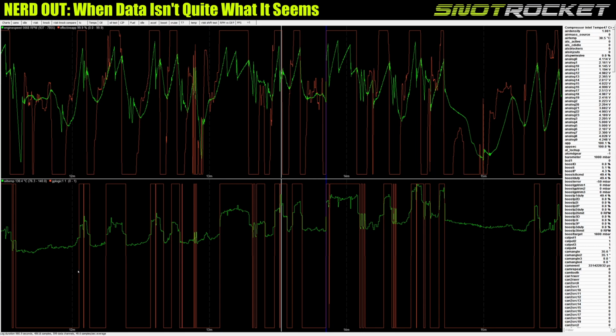So then this makes me think, well, what is it about VTEC that can be shifting the oil temperature up so quickly? So we know that oil doesn't change temperature that quickly, so it may not be a true reading. So then when you think, well, there's two possible causes, one is mechanical, one is electrical. Whilst VTEC does affect the flow of oil when the solenoid switches on and off, I can't see why it would change the temperature so significantly, so quickly. So all signs lead to it being an electrical issue, because obviously it's an electrically operated solenoid. And so then we start thinking, right, well, maybe the VTEC is introducing noise when the solenoid switches on.